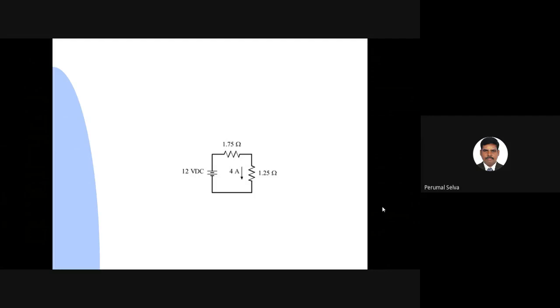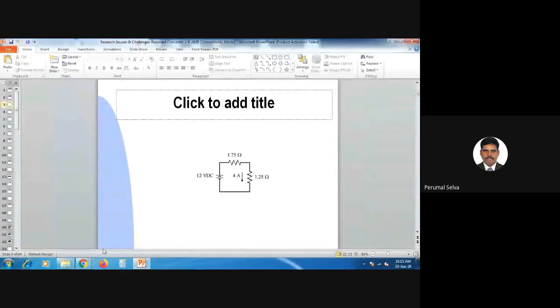To overcome the efficiency and the regulation problem, a control scheme must be introduced whereby the output voltage is measured and the supplied energy is varied in accordance with the requirements of the load. If the source voltage increases, the controller must decrease the source current to prevent an increase in load voltage. Decreased source voltage requires an increase of output current to keep the output voltage constant.